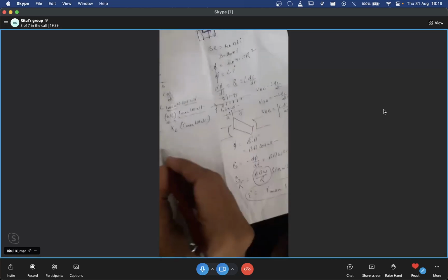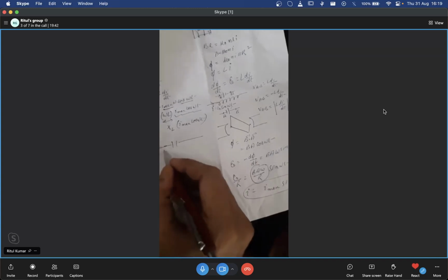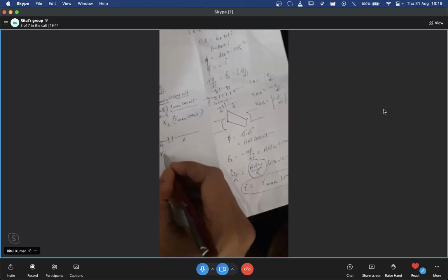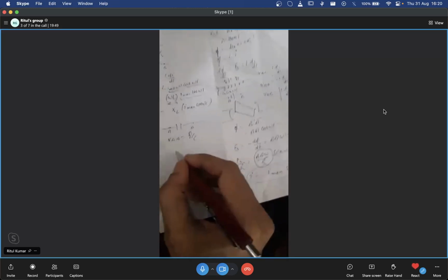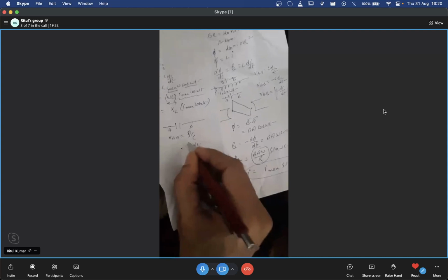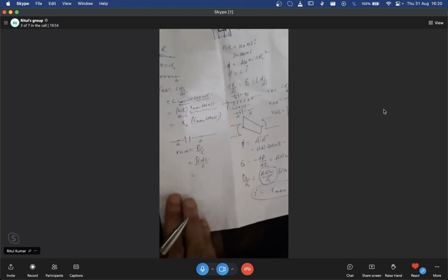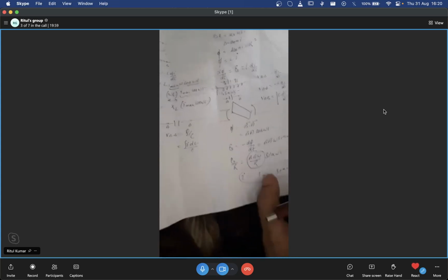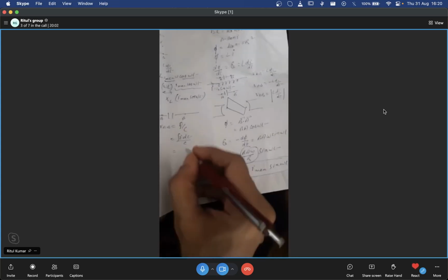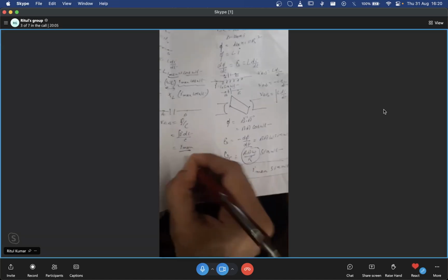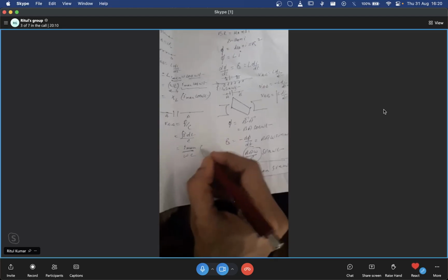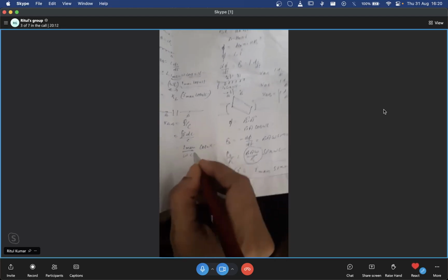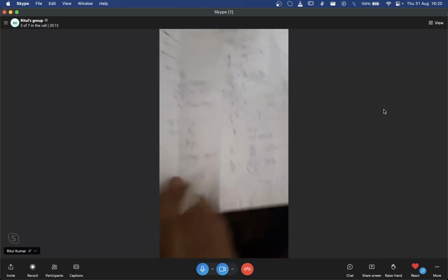I take now capacitor here. Next, capacitor you are aware of. Tell me what will be VAB. Can we say VAB will be equal to Q by C? Yes. Q will be how much? Integration of I dt by C. Integration of I max sine omega t, how much will it be? I max by omega and C as it is, right? Integration of sine omega t is cos omega t with the negative sign, correct? Do check here.